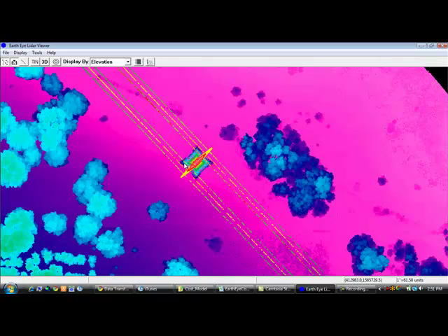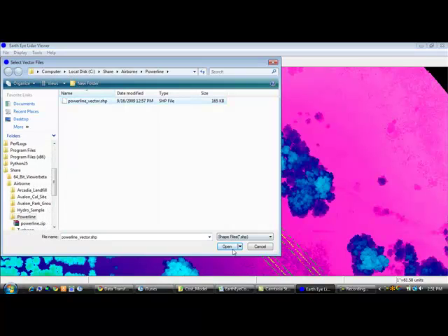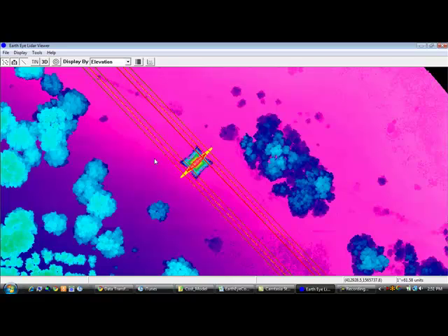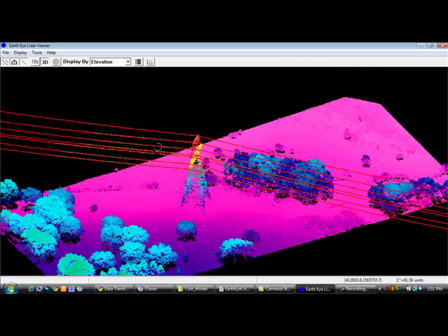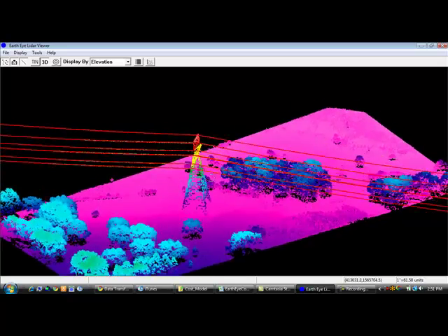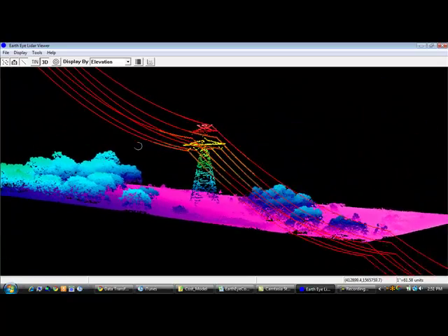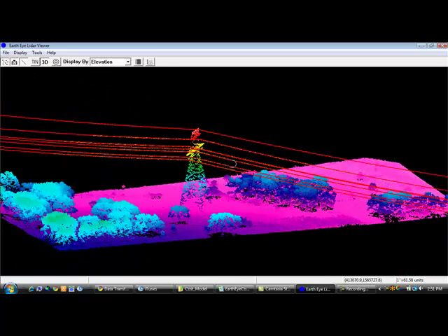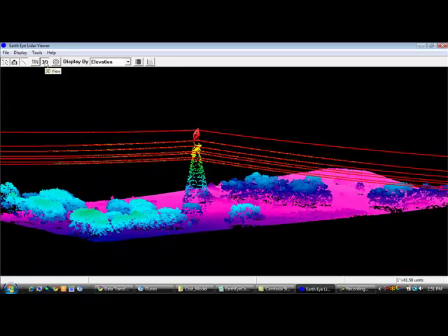so you can make decisions with the LiDAR data. One of the things that we do with this is we can run analysis of this power line data to look at any area that has grow in and fall in issues in terms of your transmission line maintenance. In this data set, I've thrown in vectors that we've created of the actual power lines themselves. You can see some of the points that have hit the power lines from the data that we collected, and then we model that data using PLS-CAD to develop these vectors for the actual transmission lines, so it models them in their current position.